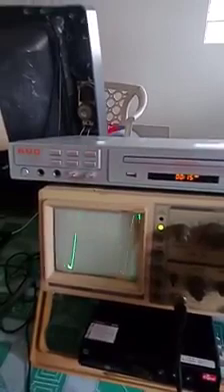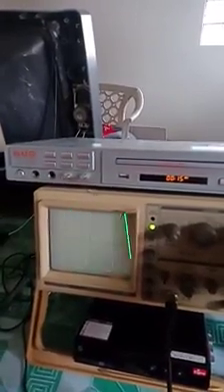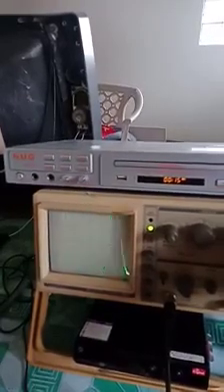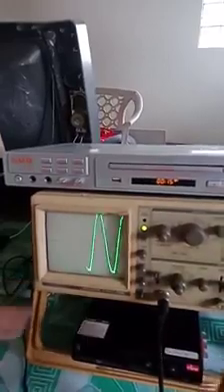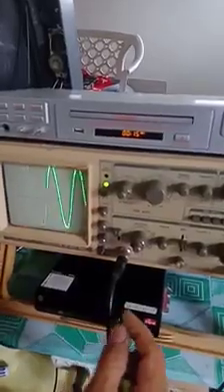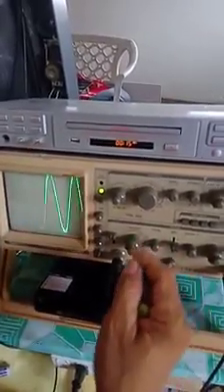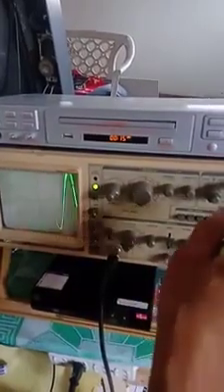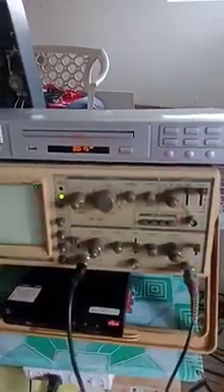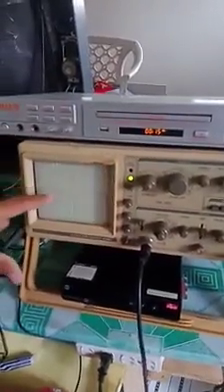Set it. We should hold it, no? We should hold. Very hard to count. Okay, guys. The waveform now is held constant, just like this, when we set the level hold control. So we can now count the number of divisions on its horizontal axis.